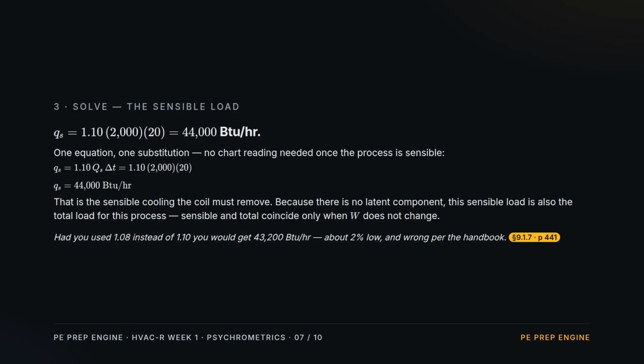Solve. Plug the airflow and the 20-degree drop into the sensible equation, and the load is 44,000. Since no moisture changed, there is no latent part. So for this process, the sensible load is also the total load. That only happens when the humidity ratio holds.